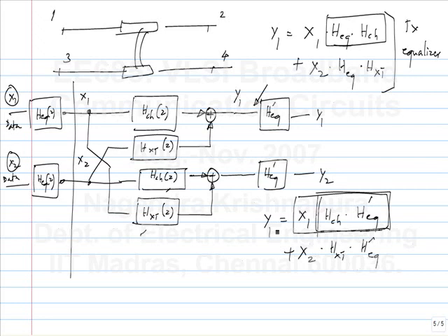So you receive exactly the same signals. So the crosstalk goes through the same transfer function. Once you decide the shape of the equalizer, okay, whatever strategy you choose, to do zero forcing or to do something else, you will do the same thing in the two cases. Okay, there is no difference between the two cases.